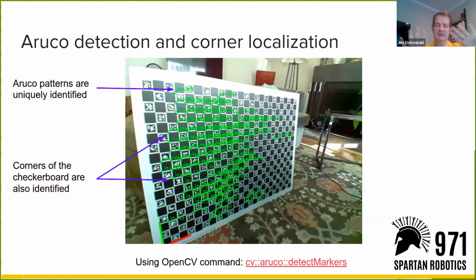Just to really drive that point home, a typical calibration procedure might include 30 or 40 or 50 sample images where we've taken the board and moved it at different angles around the camera to get good coverage, so that we're getting sample points all around the camera lens. You want to really, especially around the corners where the distortion is the most, make sure you've got good samples for the algorithm to be able to do a robust estimation of the intrinsic calibration.